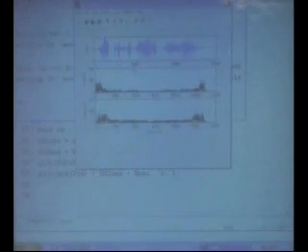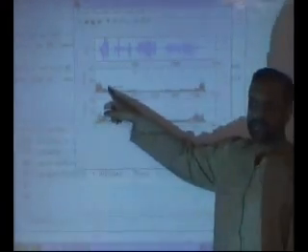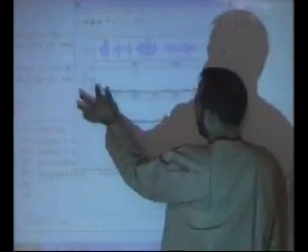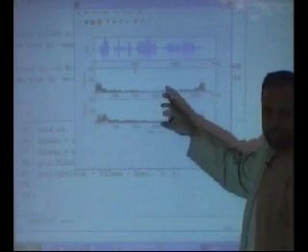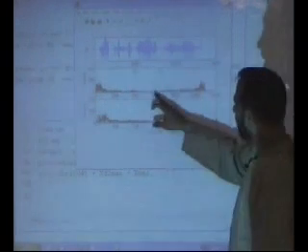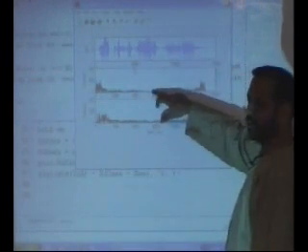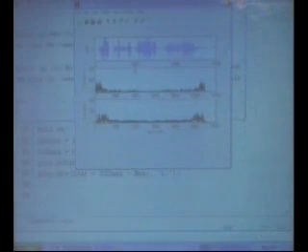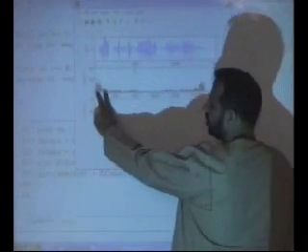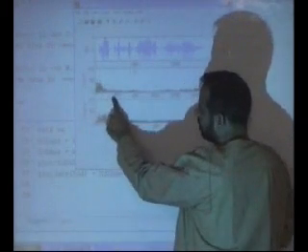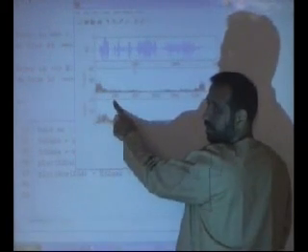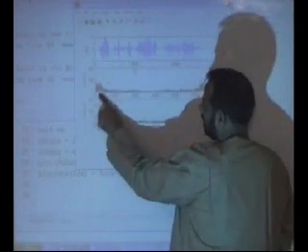DSP1. So this is the original voice. Look at the spectrum. So this is in time domain, and this is in frequency domain. Usually voice activity is here, and as you can see, the sampling frequency is around 11 kilohertz. So that's why you see pi here. It's sampled at approximately 11 kilohertz. But you see most of the voice activity is only from 0 to not even 2 kilohertz. Okay, most of the voice activity is here.